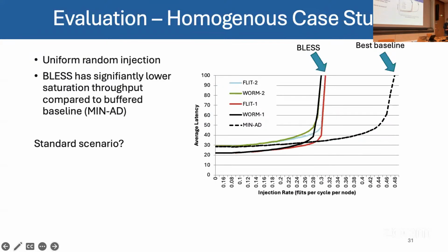So first of all, is this the latency for a flit to arrive, for the entire package to arrive, first arrival, or is it when the package is totally received? This is just the latency of single flits, in general the average latency of flits from source to destination.